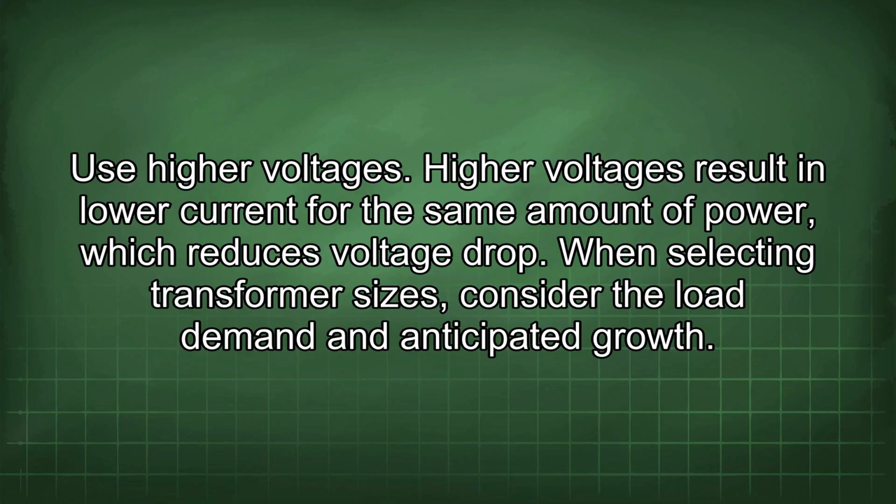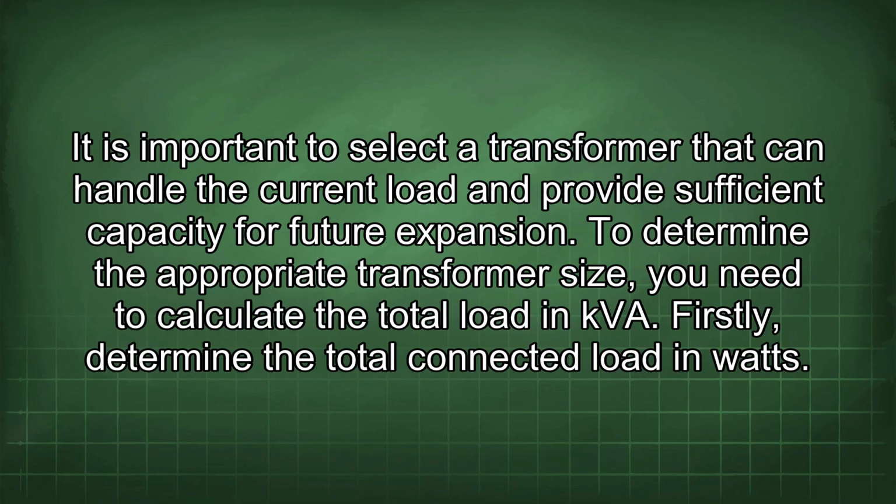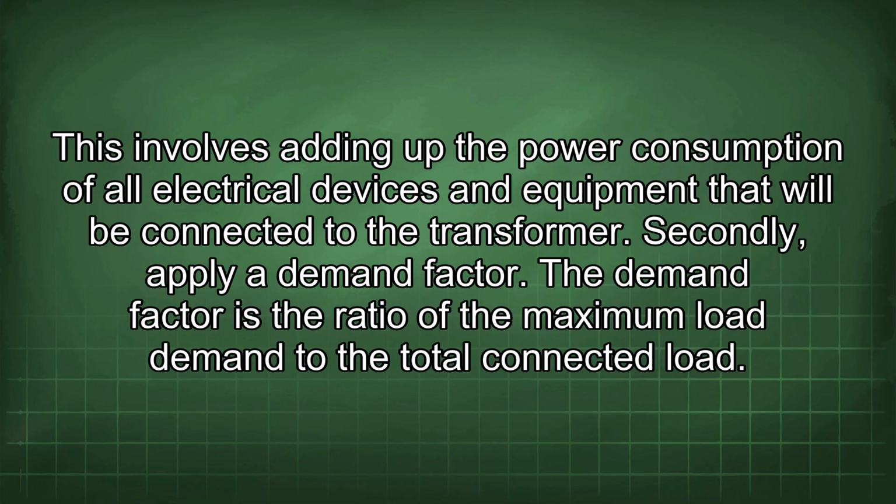When selecting transformer sizes, consider the load demand and anticipated growth. It is important to select a transformer that can handle the current load and provides sufficient capacity for future expansion. To determine the appropriate transformer size, you need to calculate the total load in kVA. Firstly, determine the total connected load in watts. This involves adding up the power consumption of all electrical devices and equipment that will be connected to the transformer.